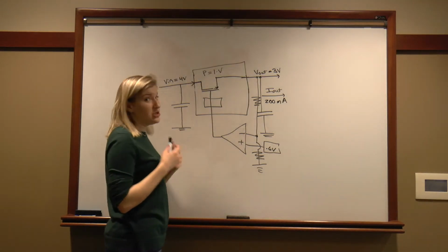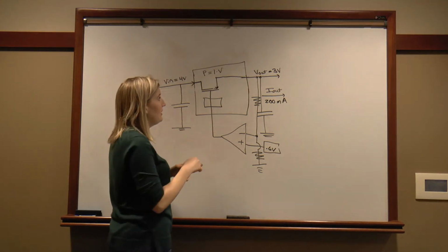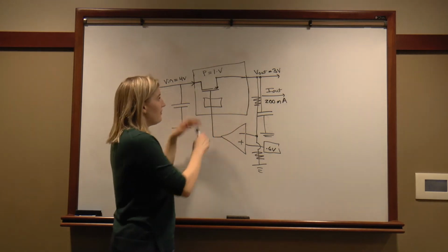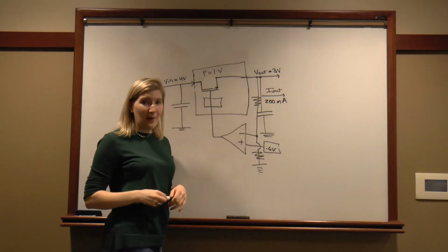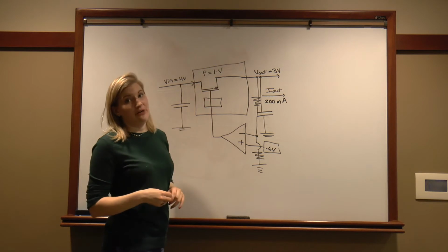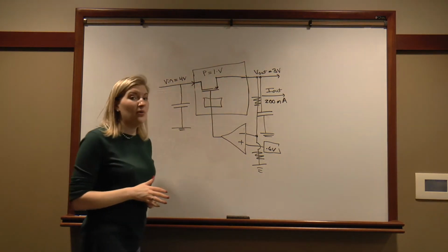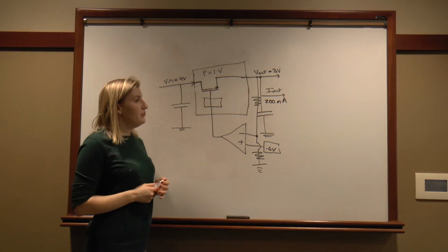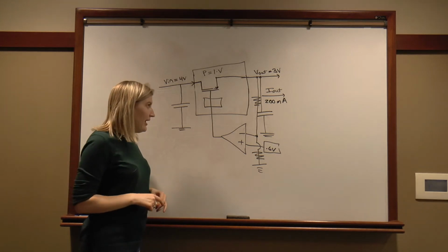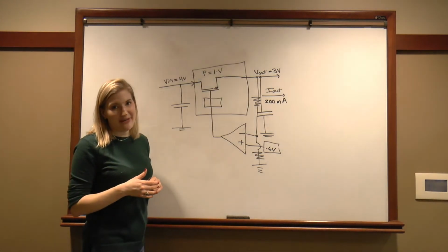But if we're more concerned about heat and power loss and efficiency, or we have high currents, or we have a big voltage differential between our input and our output, this becomes a concern. So we need to think of a more efficient way to regulate our voltage. And that brings us into switching regulators.